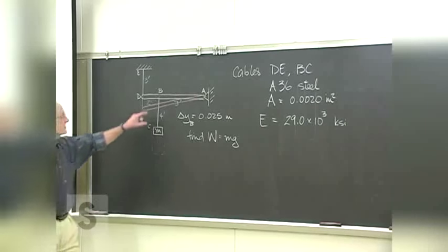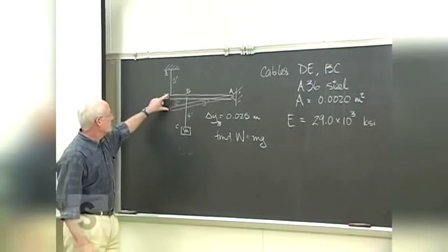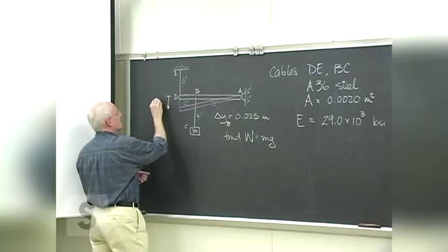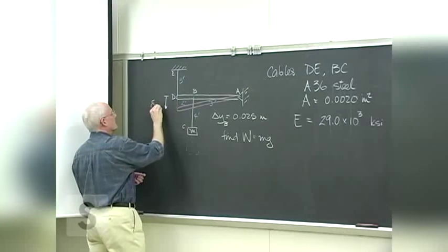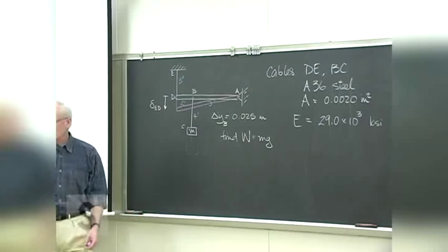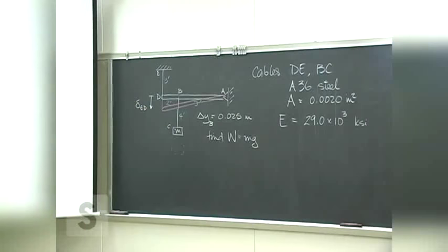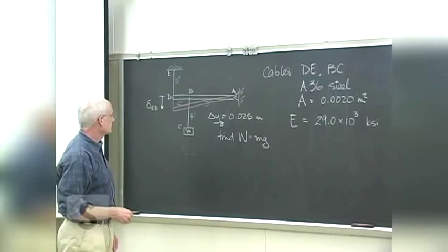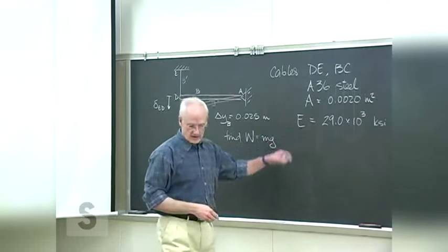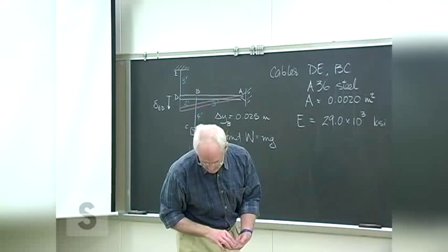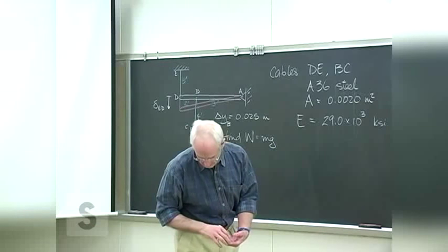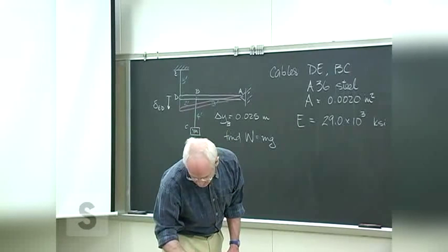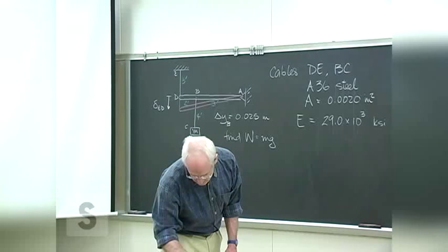By geometry, you can find how much the cable here elongates. That will actually be its deformation. Then you can find what load must be in there to cause that.